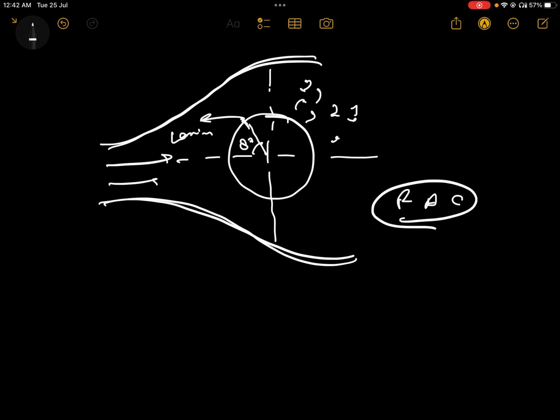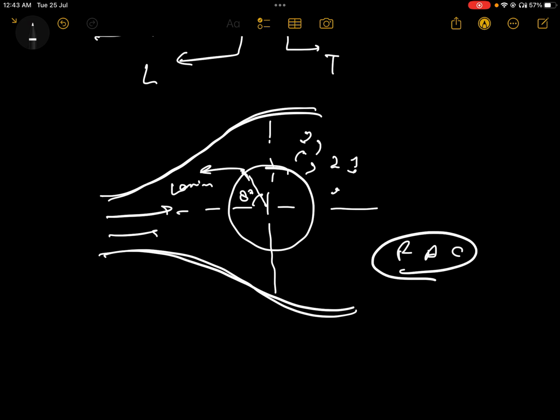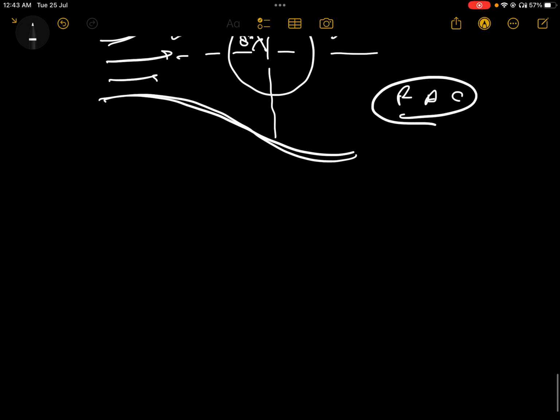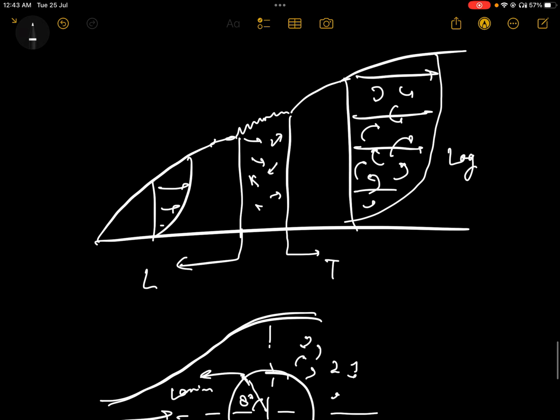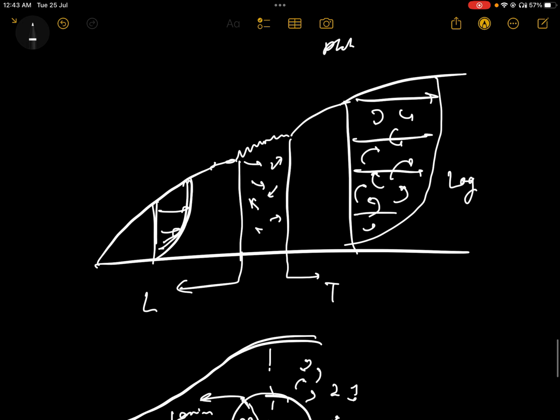So for any given velocity with a given surface temperature of the body, the local convective heat transfer coefficients in the turbulent domain are always greater than those in the laminar region. More often, we come across laminar flows during forced convection heat transfer over a flat plate. So, for laminar flow over a flat plate, the velocity distribution within the laminar hydrodynamic boundary layer can be given as, actually it is derived, so I'll directly write it. The velocity profile is what we get for the case of laminar flow.